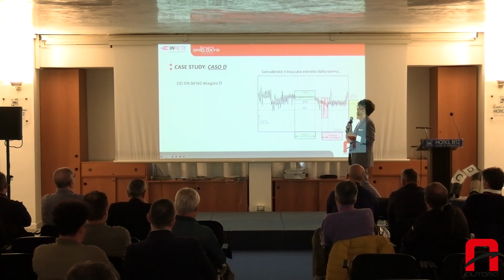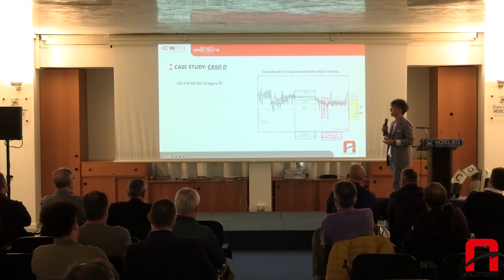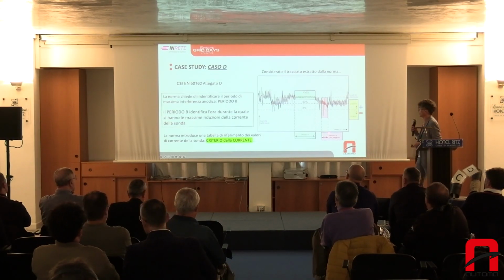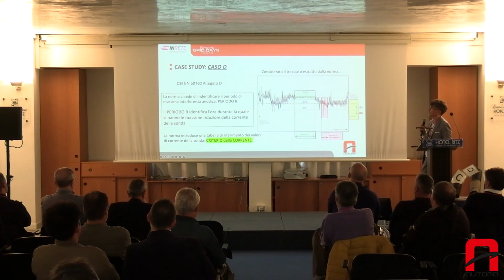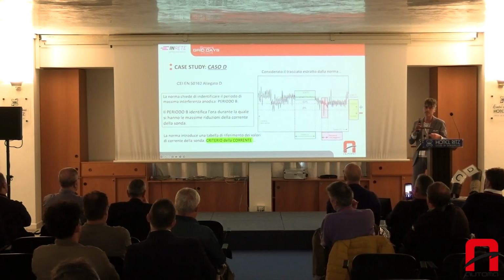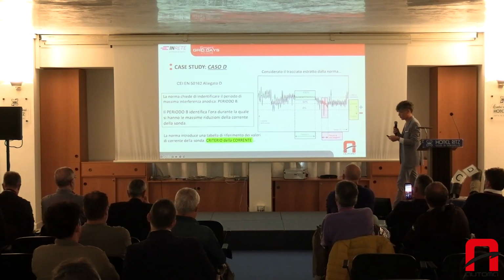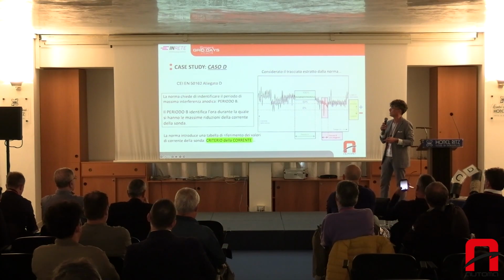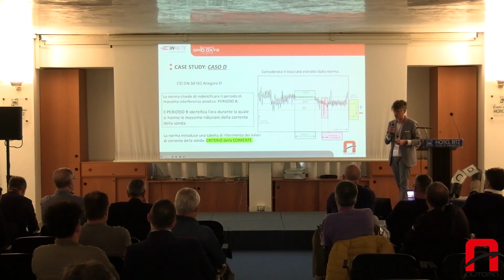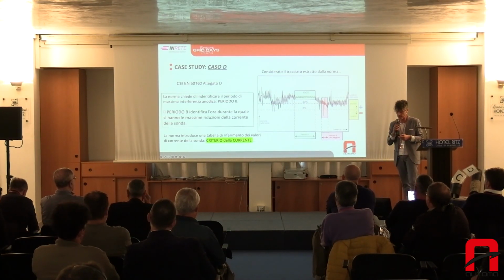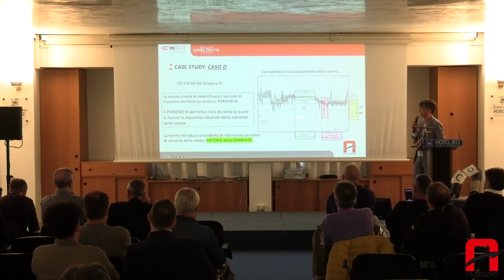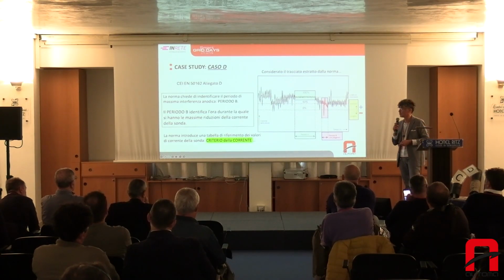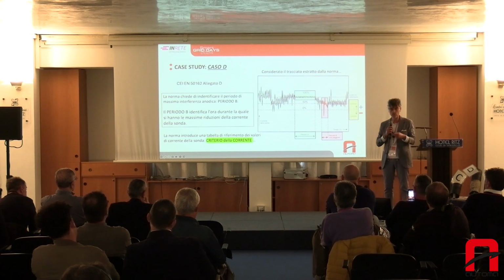So this same graph also tells me that there is a B period. A B period is a period in which you have the highest anodic interference. So it identifies an hour in which you have maximum reduction of current towards the probe. So you have a more anodic situation.